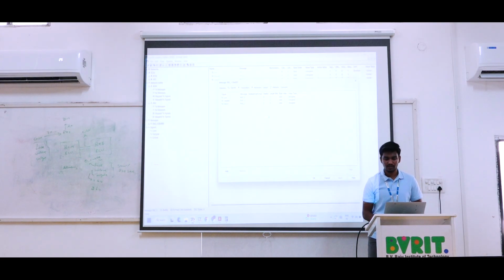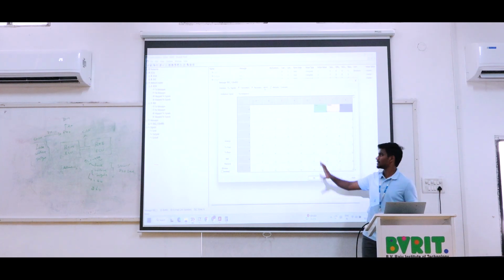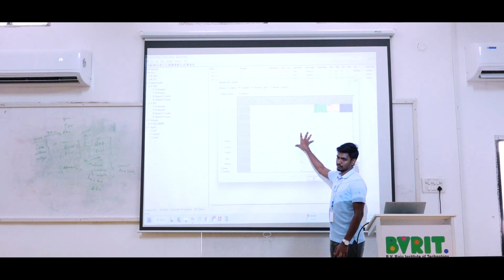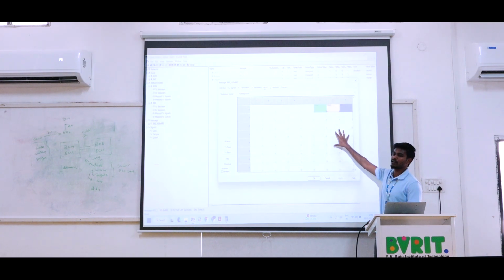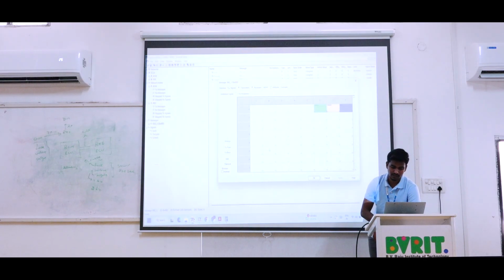Now where we can check is this layout. After signals we are having transmit and receive, it is a receiver ECU. Third one we have the layout. So this is the control, data field column. Here only we are going to store our entire data. We are having this message up to 64 bits.